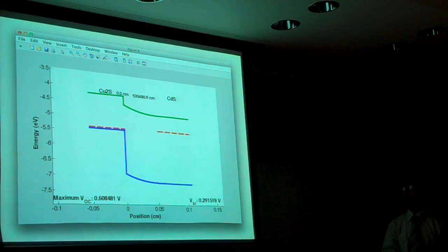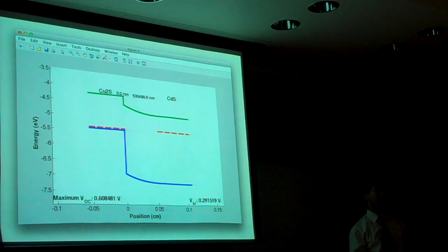So this is what the final figure will look like. And so again, we have the conduction band, we have the Fermi levels, which are now at the same Y level, and then we have the valence band at the bottom. So also in the bottom left of the figure, Plot Junctions has gone ahead and calculated the open circuit voltage, which is the voltage that you would measure across this junction if there were no current. And this is the maximum theoretical voltage that you might be able to get if you're building a device like a solar cell. So we're going to come back to this in a later slide.